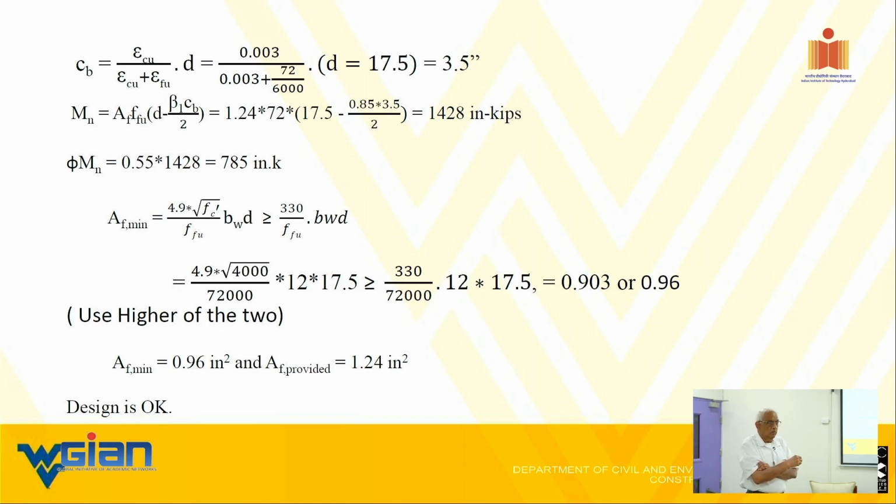In this case, that phi Mn must be equal to ultimate moment, okay. Please note, this moment, phi times Mn, must be always higher than M sub u. You will see that when I run what I call an analysis problem. You will see that in a design problem, that M sub u is inclusive of your load factors.